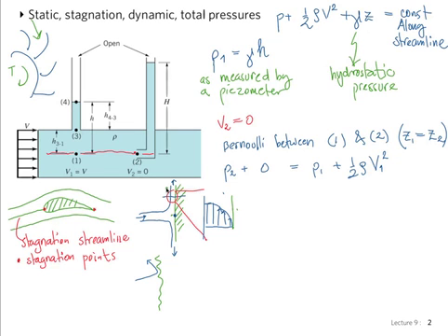Okay. So we are looking at this situation here where we have applied Bernoulli's equation exactly on the stagnation streamline, which is drawn in red on our sketch of the situation. So velocity at 2 is 0 for the reasons we've just described. Velocity at 1 is the velocity we're considering now, again simplifying the situation, a uniform velocity inside this whole pipe, and it's v1, our average velocity.